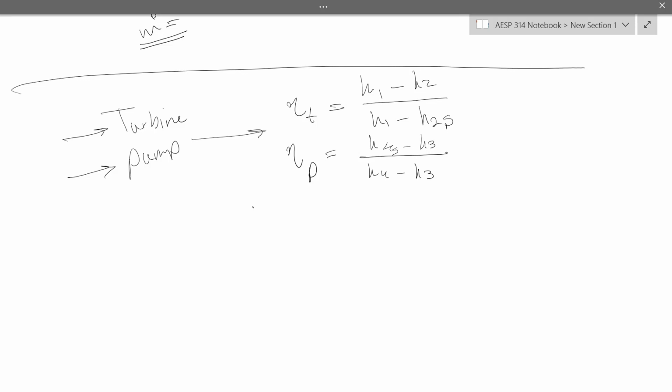So, in the previous example, with the methods we used, we actually found the isentropic enthalpy, right? If we were given a pump efficiency, we should have plugged all of the values in to find the actual enthalpy, right? Does this make sense? Okay. So let's move on.